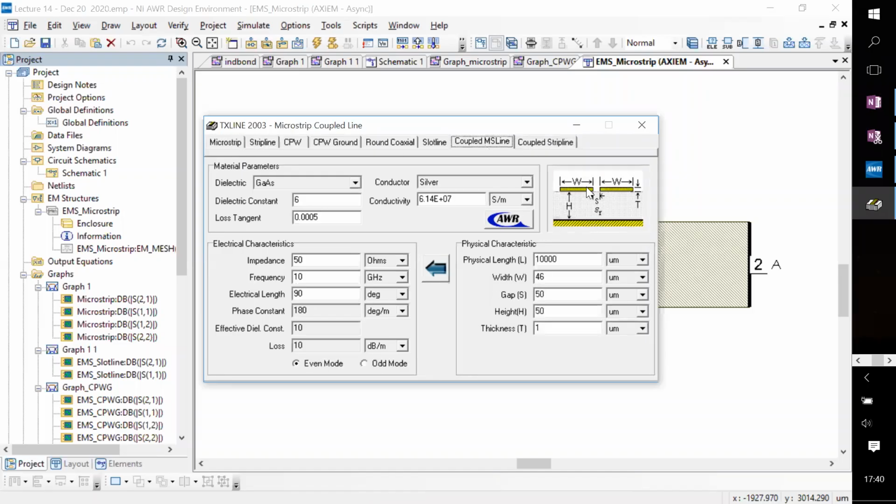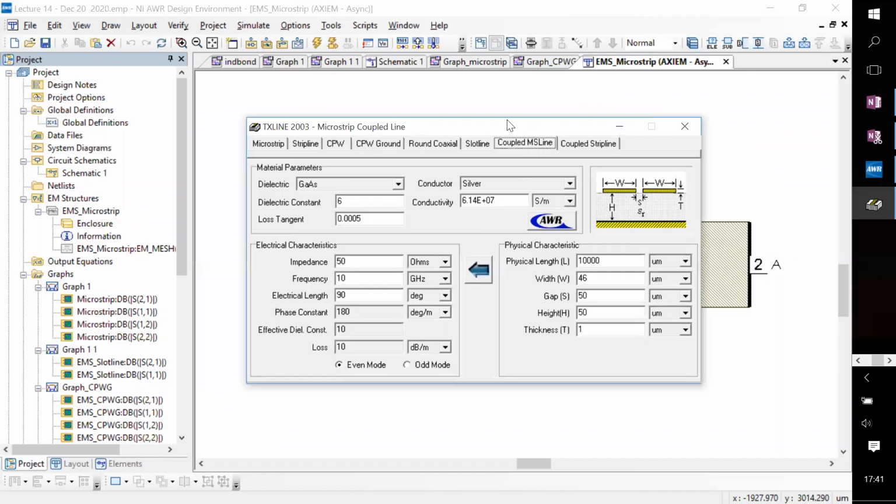So now you have two sort of center conductors in both cases, and microstrip doesn't have a dielectric on the top as opposed to a strip line, which has a dielectric and a ground line. So this is the symmetric one. So these structures are actually used for some very common devices, one of which I will briefly introduce today, and then one of them might actually also be the device one of you will design as part of the course